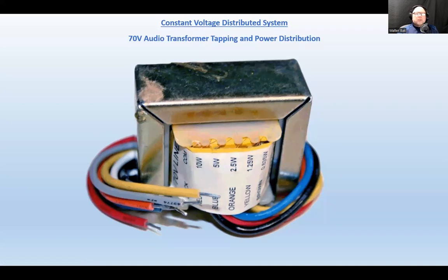Now, just as a general rule, if it's a school PA system, which consists of hallway speakers and classroom speakers, in order to accomplish a proper volume balance if an all-call page is made, the hallway speakers would be tapped at 1 watt each, and the classroom stations would be tapped at quarter watt each.